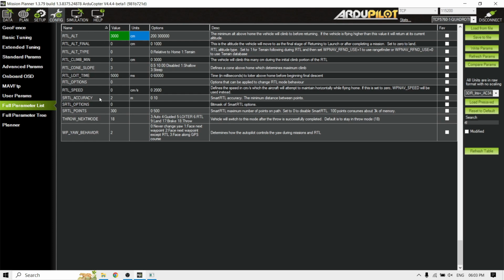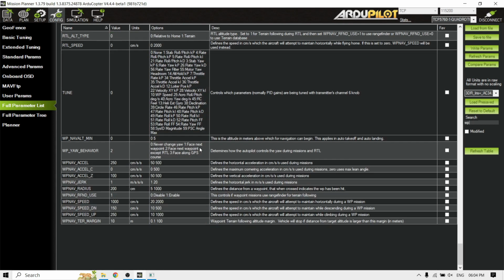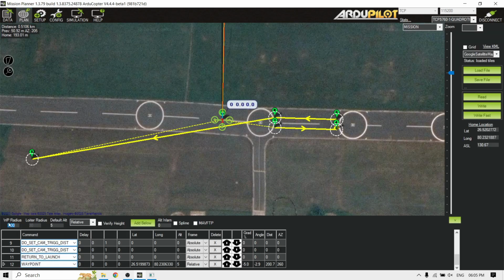And regarding altitude itself, we have so many different parameters. It depends. Okay, I'll just get back to default and I'll keep it at 15 meters. Then let's check WP, that's waypoint. In waypoint you can see there's waypoint navigation speed, then radius, that's 200 centimeters. So I'll change it here and let's check whether it will update over there. I need to write this. Are you sure? Yeah, okay. Let's check over here. See, here it has updated. 7 meters it had come.